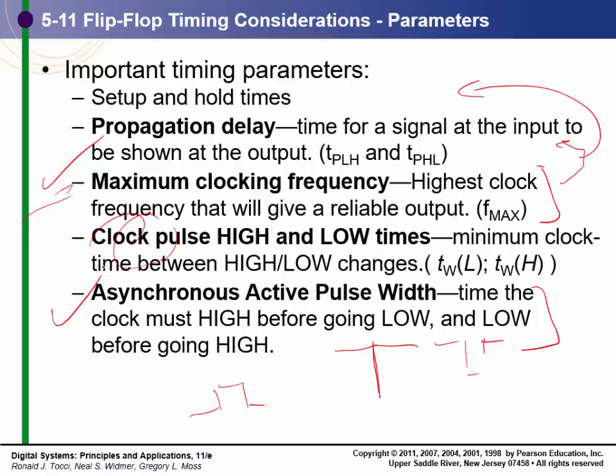That's what makes life very interesting when you're trying to push leading edge. You design your circuit in VHDL, or you use your schematic diagram, or you write Verilog, or you do a mix in between, and then you do a complete compile. It works great. You make a minor change, and all of a sudden your maximum clocking frequency dropped 20%, and the circuit blows up in your face. Not literally blows up, but doesn't work right. It can get quite frustrating.